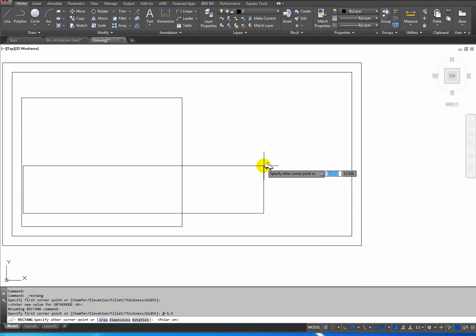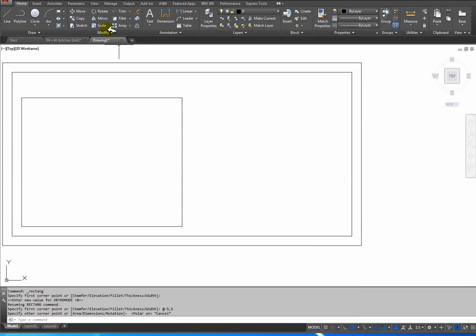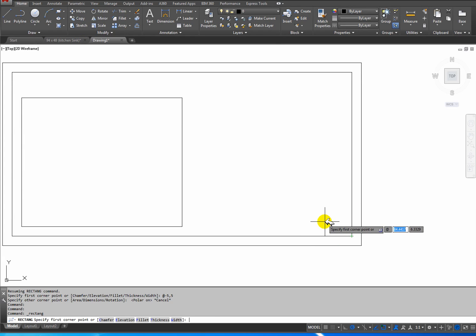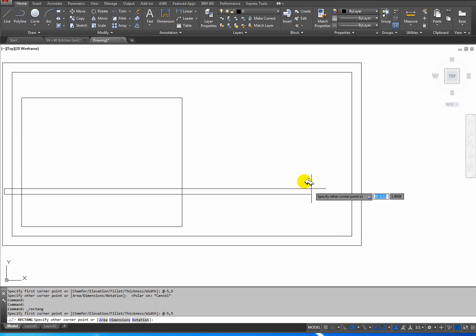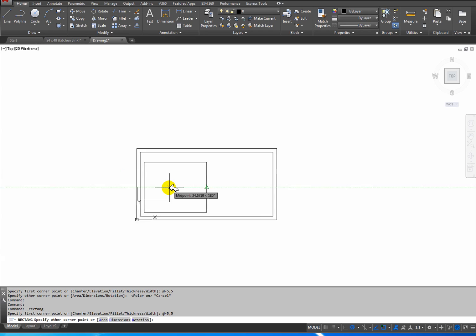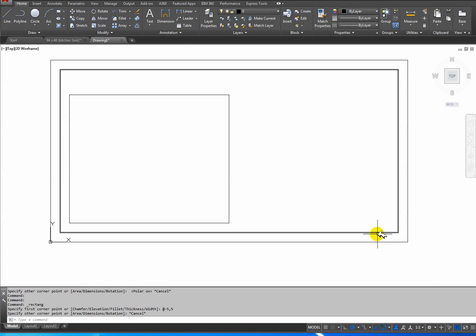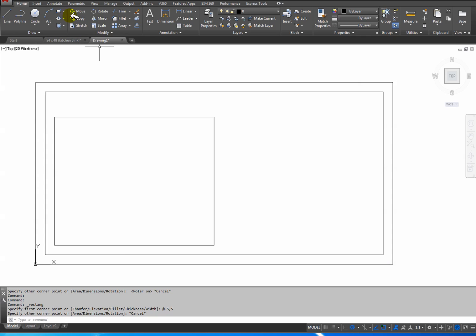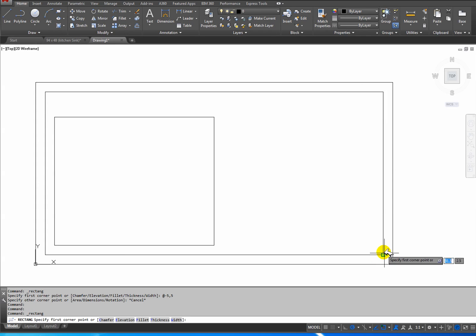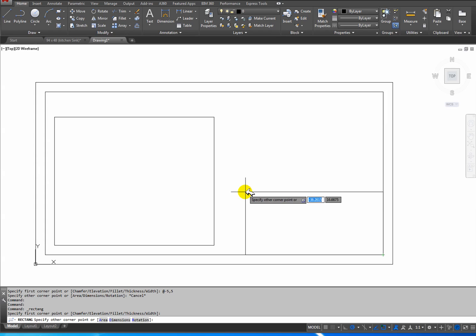And it picked up, oh sorry, I don't know what happened there. Let's try again. So rectangle, show that point, type the word at, minus 5, comma 5. It keeps going to that point, for whatever reason. So I'll show you another way of doing it. This time I'll select that point straight, and I'll type x will be minus 34, comma, the y value will be just 2.5.